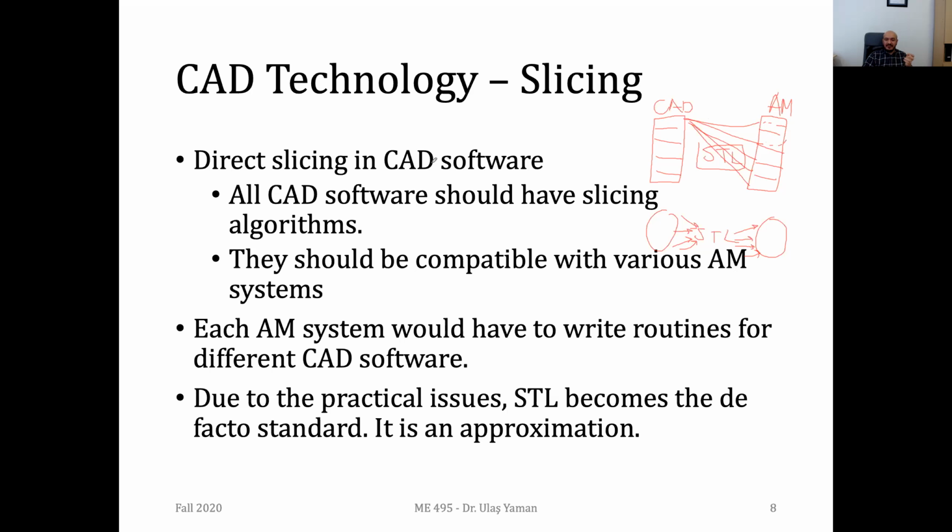We'll discuss these in the next chapter, but I can say that in my research, in my lab, we prefer to use such an approach. We love to do direct slicing. And another question about the quality. Yes, the quality is much better in direct slicing, since we said that the STL file is just an approximation. We can have much more freedom, much more accuracy with direct slicing.